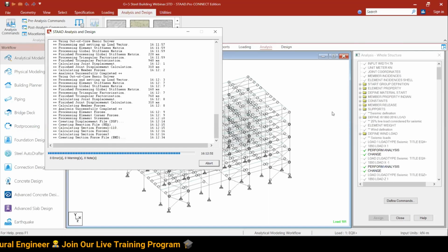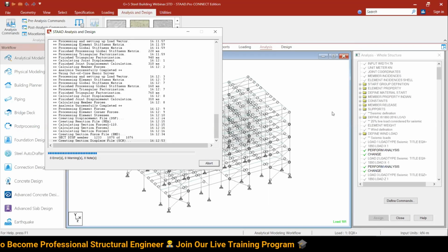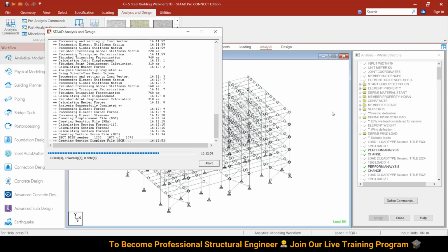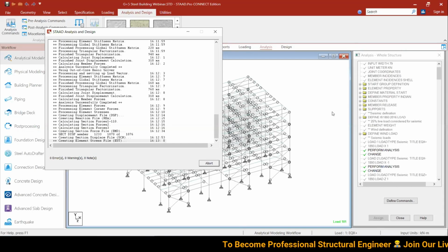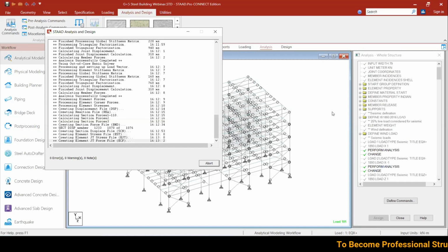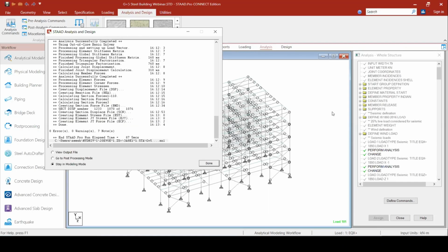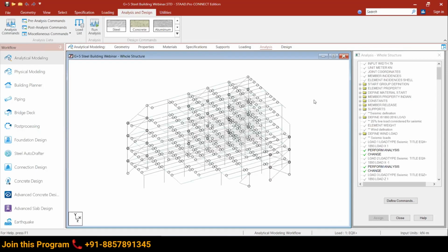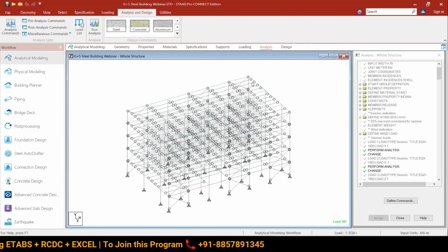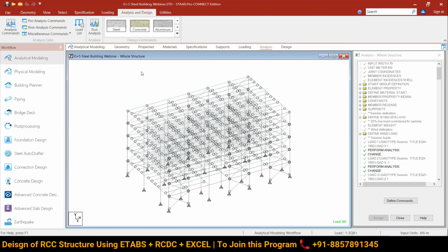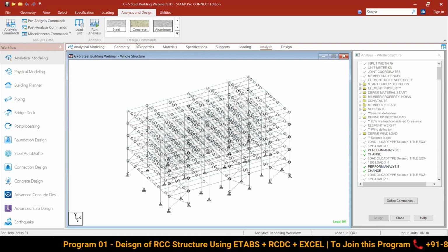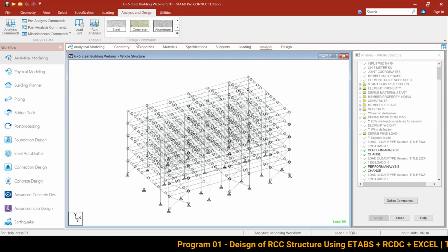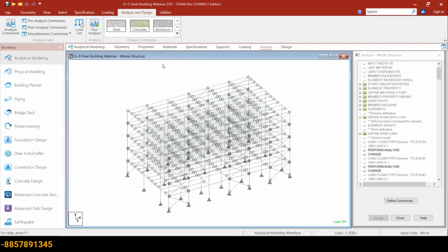The reason I'm asking is that with primary and secondary beams, especially from the design point of view, the ribs of the deck should be parallel in one direction and perpendicular in the other. This will affect the lateral restraints and the torsional buckling restraints. Yes, I understood. It could be modeled, but you need to provide a plate element and then do proper meshing. If you also want to model the shear lugs, I think that is not possible, because that could be another critical thing.